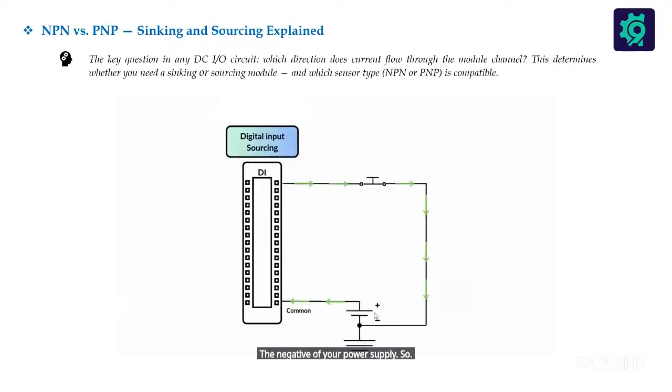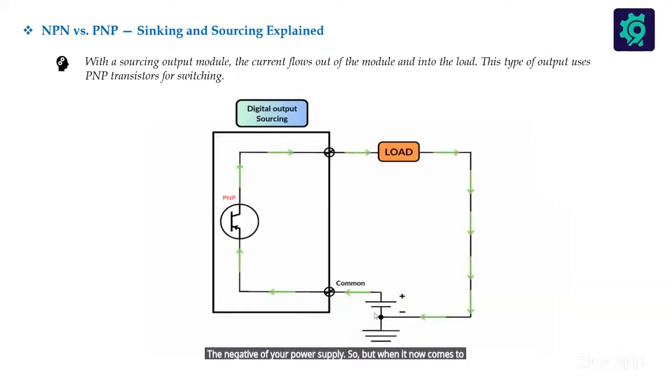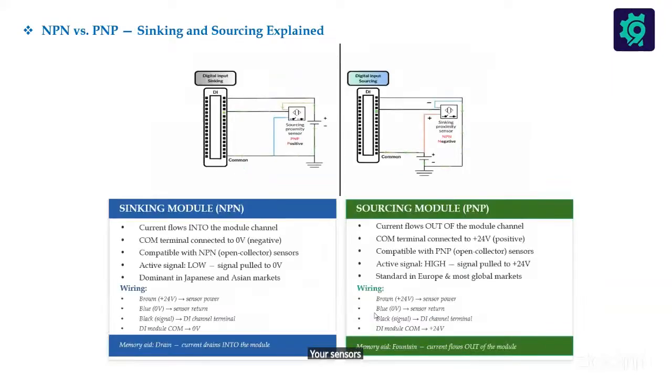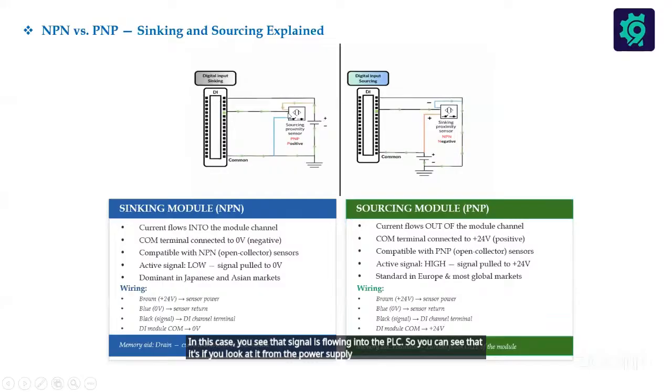But when it now comes to your sensors, if you look at these sensors, in their own case, you see that signal is flowing into the PLC. If you look at it from the power supply end, and of course the sensor is in play here, the PLC is sourcing from your sensors and then sinking out into the power supply.